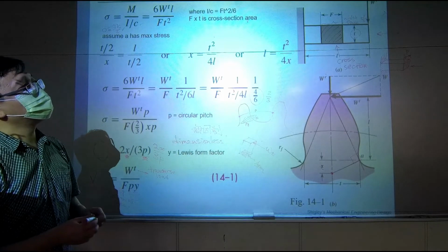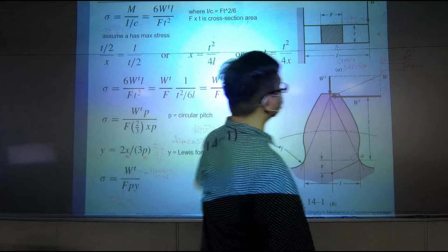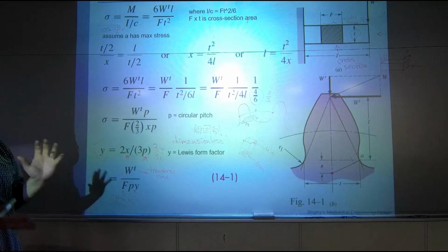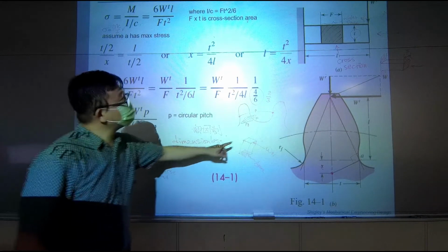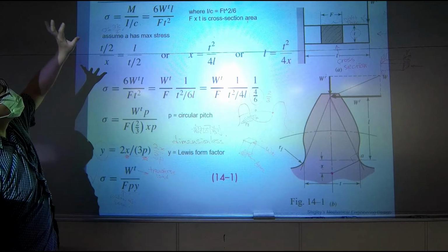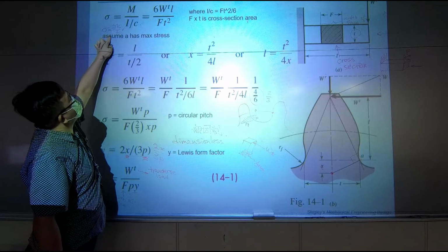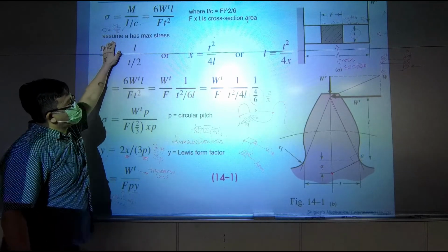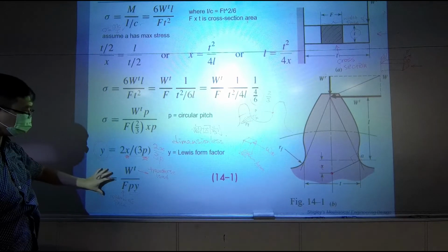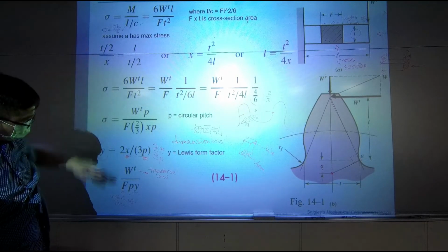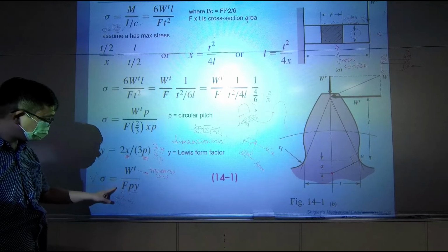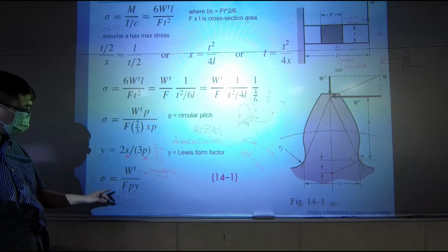It's not like you just use F times T. Because Fpy ends up with some number that is not F times T. But he derived from sigma equals Mc over I, and he has a shape parameter which is dimensionless. At the end, it equals a very simplified model, and this area right here equals Fpy.